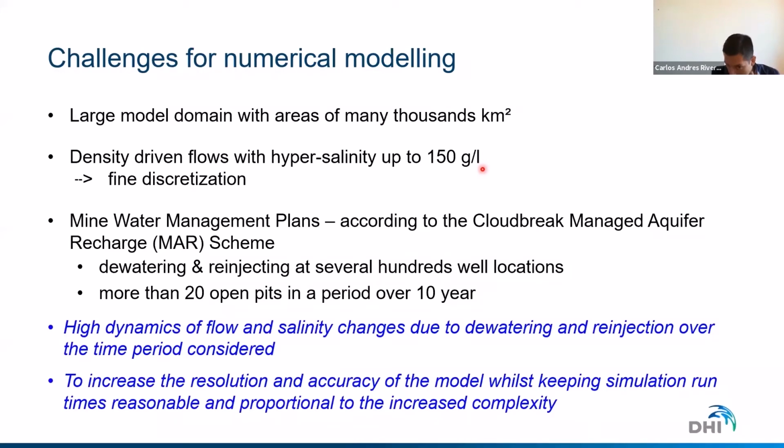This is a lot. Numerically it means that you need a stable model, and to solve this you require a high level of discretization, a fine discretization. Here, FEFLOW can do the job because we can work with local refinements in the triangular mesh. Nowadays, we can do even better because we have access to a combination of triangular and quadrilateral meshes. We have dewatering and reinjection schemes of several hundred well locations. This makes it complicated, so we need to script something, using the open programming interface to reinject the water.